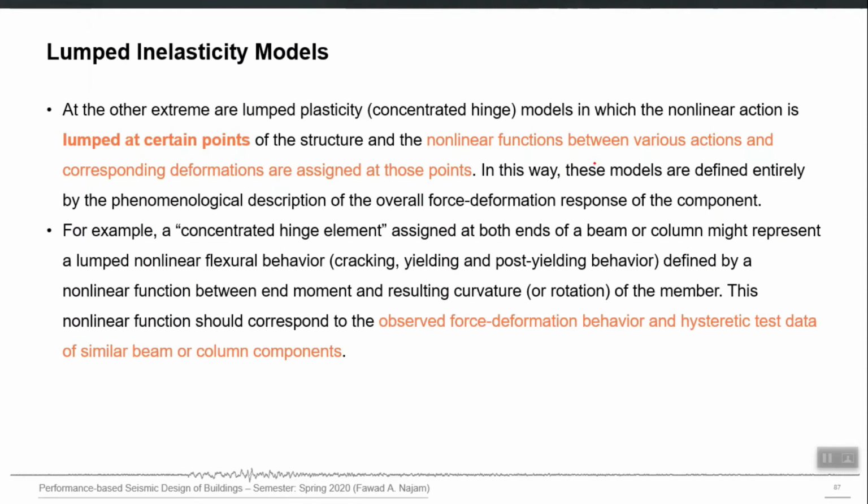The actual nonlinear deformation may be distributed along the length of the element, but we assume that the whole effect of that nonlinear deformation is lumped at a certain location only. So that model is simple also, but at the same time the overall inelastic effect can be captured, right? In these kinds of models, you may not be able to see a crack which is traveling in a particular element when the load is being applied. But in the continuum models, you will be actually able to see that.